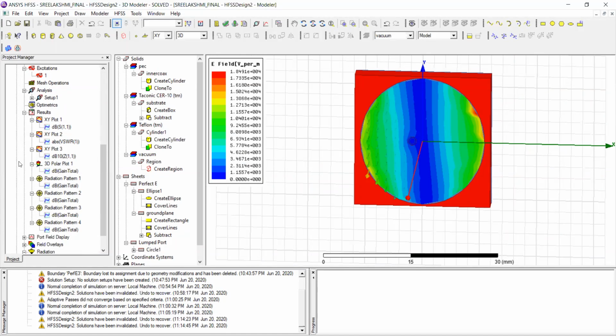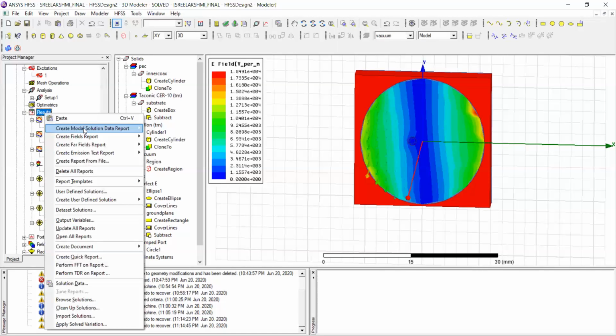That is why, for critical applications, we'll be designing an antenna with circular polarization. Like you can see the satellite antennas and all, it will be in circular polarization. And if I design my antenna for circular polarization, I want to check whether it is circularly polarizing.